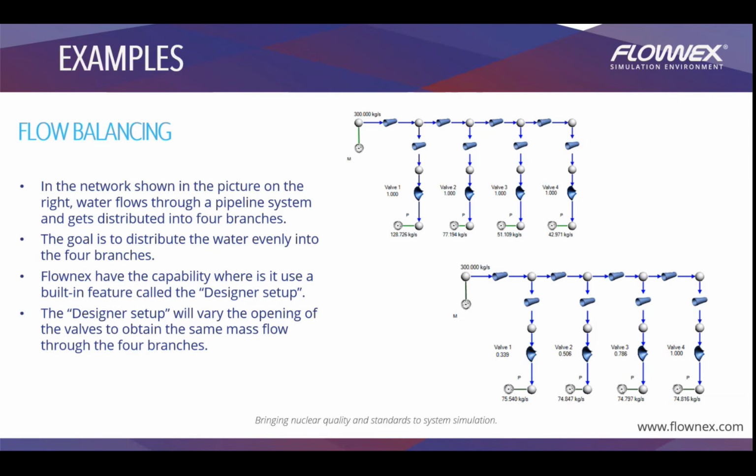It uses the Designer setup, a feature that's available in Flownex. So you can use that specific feature in order to design the valve sizes to obtain the desired mass flow rate.